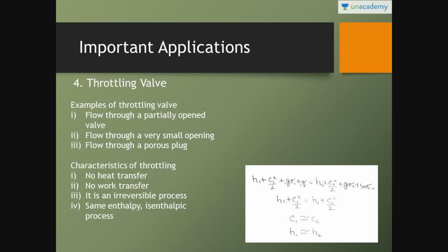This is very important. What is the throttling process? In a throttling process there is no heat transfer, and there is no work transfer. It is an irreversible process, and the enthalpy is always constant. It is the same enthalpy, or isenthalpic process.